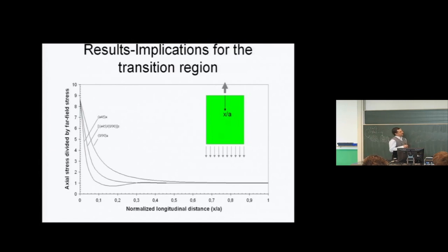Then I have this plus or minus 45, 0, 90 symmetric, again 4 layers, and that one is by definition quasi-isotropic. The 0, 90 is the one that we mentioned here. So we have 2 layers of this and then repeating symmetrically. So that's the quasi-isotropic with the same stiffness in every direction. And finally, we have a 0, 90, so it's the same one as the plus or minus 45, but rotated by 90 degrees. So that one now gives us the highest stiffness that we can get using fabric material in the X and Y direction. So this would hopefully cover a wide range of stiffnesses.